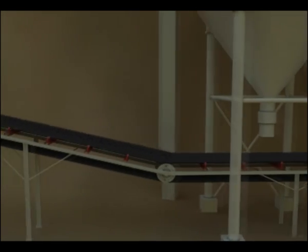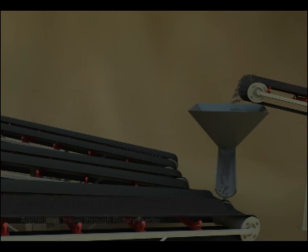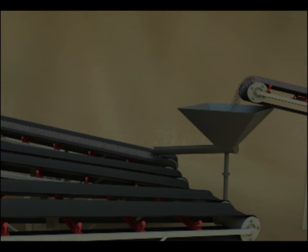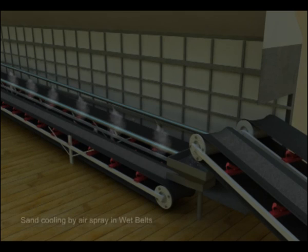A conveyor carries aggregates from the silos, one size of aggregates at a time, to the rotary feeder. The rotary feeder mechanism directs the aggregates flow to the respective conveyors and subsequently to the hoppers in the wet belt system. Hereon, all the facilities are covered and insulated to avoid heat loss.